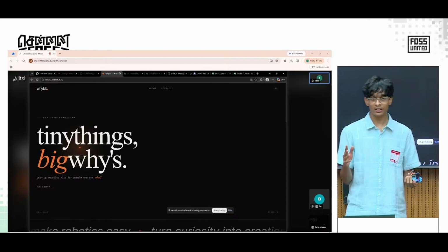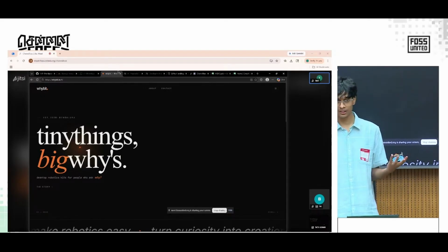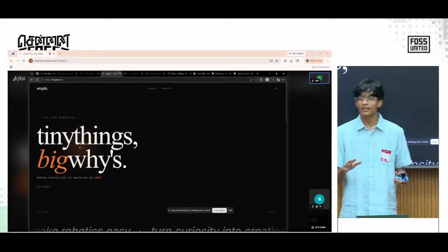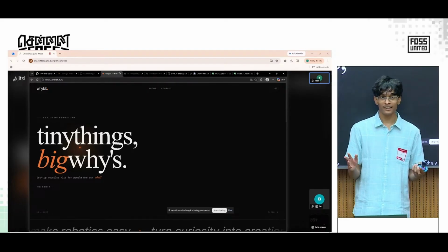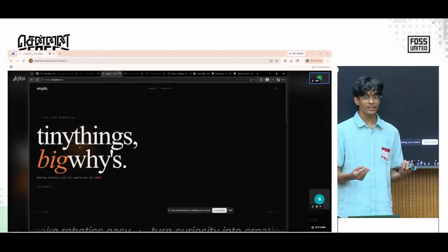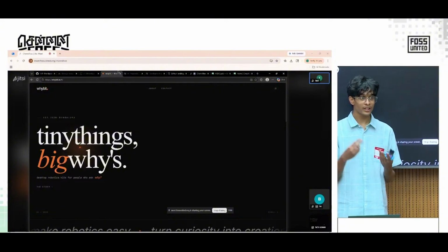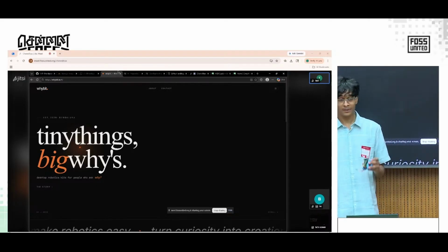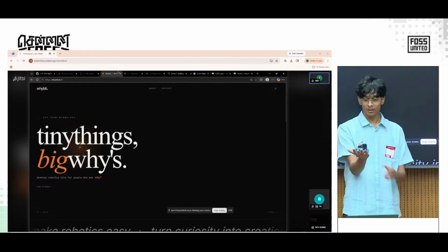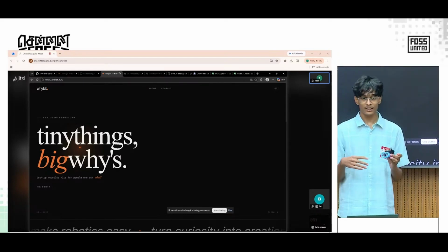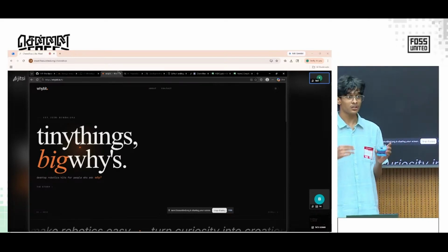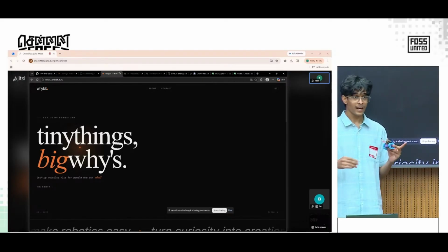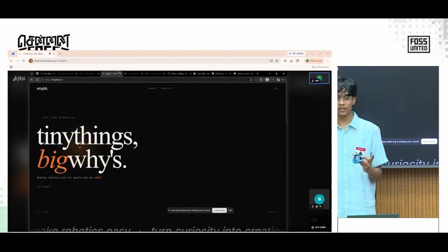My first design was just adding 2 motors and wheels to it, and that was really complicated. If we added 2 motors, then we need a motor driver, and for the motor driver we again need a boost converter, and that again made it very big. I wanted to make something very small, which could fit on your hand. So the solution I implemented was to use servo motors. Servo motors have a built-in motor driver within them, so you don't have to install an external motor driver for that.